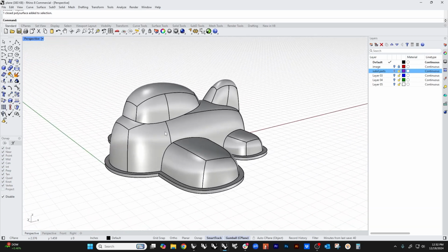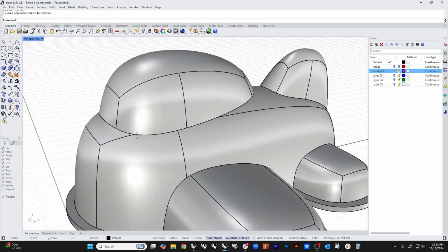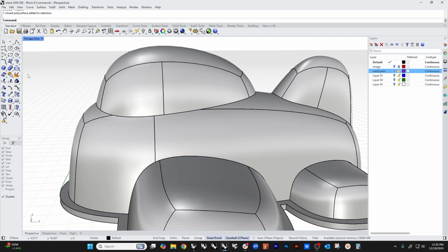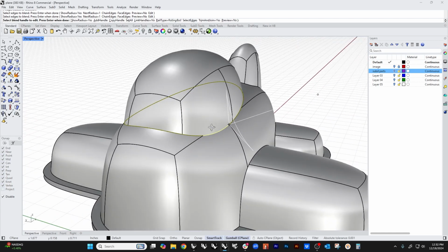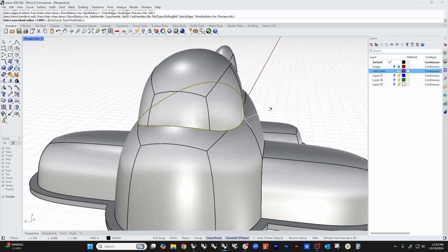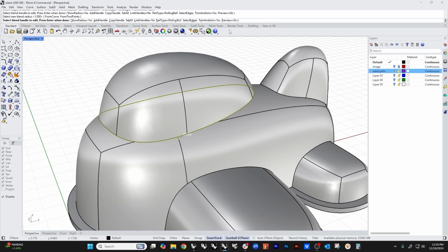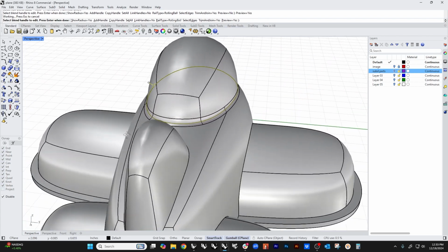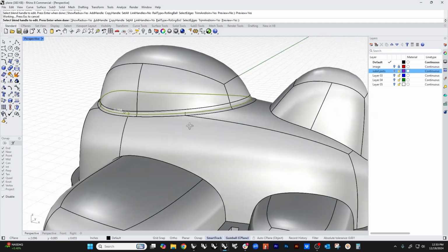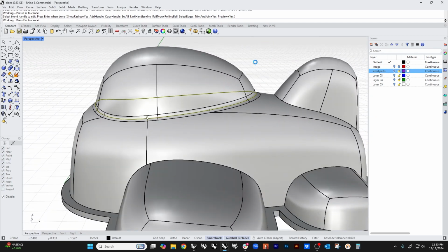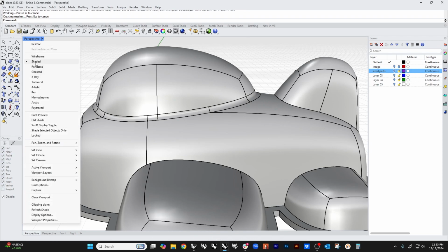Now the last thing that we can do is have some fun trying to clean up our transitions. And because these are simply NURBS objects, we can just come in and add our filleting and blending. I'm going to put some small little blends on here, something not huge. And I'm using blend and not fillet because I like how blend looks better. Blend is based on continuity, and fillet is a ball. And ball fillets tend to not be super pretty all the time.